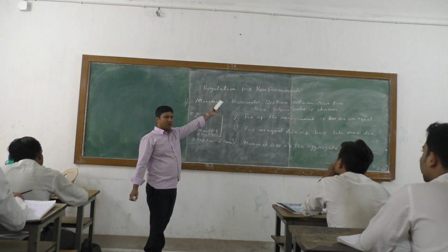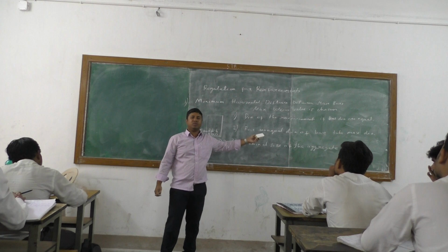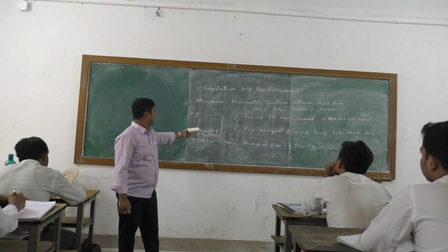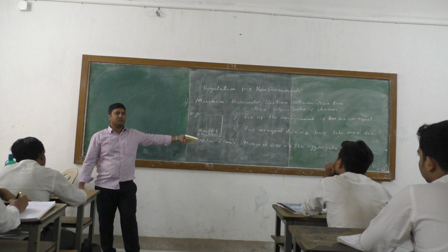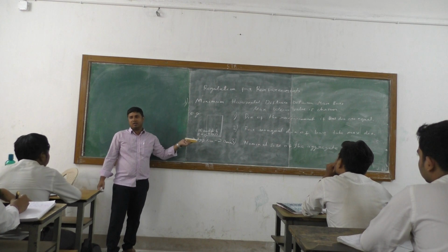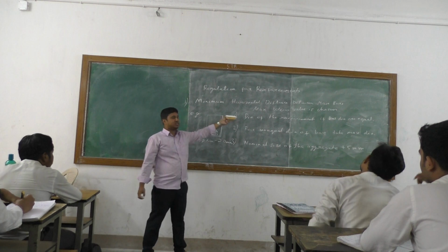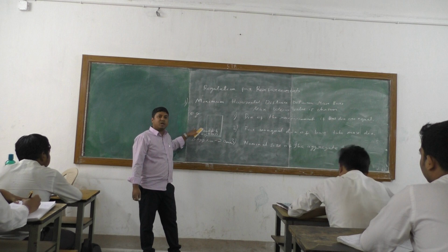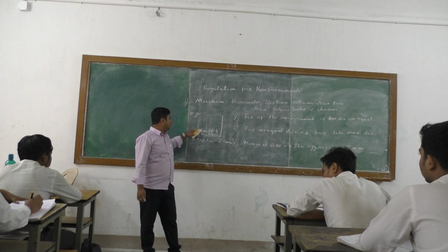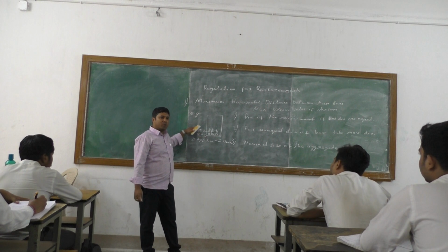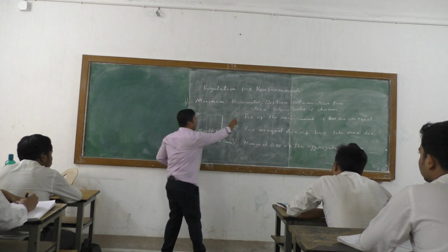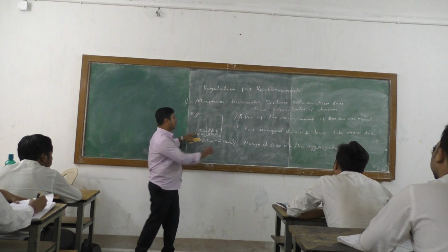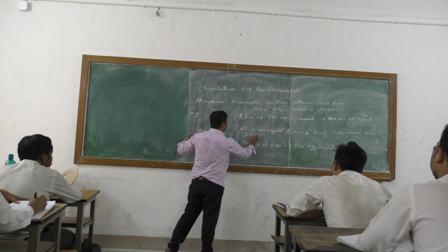Now you tell me what will be the minimum horizontal distance between the two bars. 16, 20 and 20. Now you tell me, what is the first criteria? First criteria: the maximum diameter of the aggregate, the diameter of the reinforcement bar. The diameter of the reinforcement bar is unequal, so the first cancels out. The second option is that it is unequal. If it is unequal, we will go for the maximum value. So from the second criteria, we are taking 20 mm.